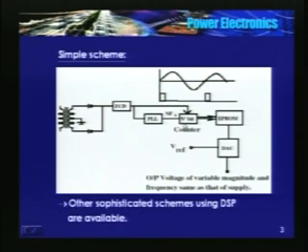Now this n bit counter requires a clock. There has to be a relationship between this clock and the supply frequency. So if there are 512 locations here, the counter should get 512 clock pulses in this period. So what I will do is I will use a PLL as a multiplier.